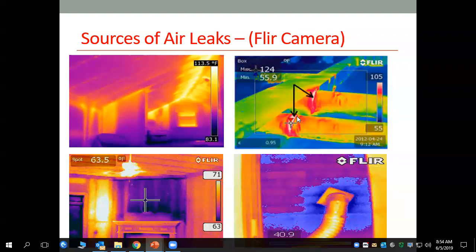And then on your connections here, on your duct where it's connected, there are obviously leaks. That could also be moisture at some point. That's on a long trunk line, and then the ducts are coming off. You see the fireplace, that's not sealed properly behind it. I'm not even looking at the actual fireplace itself, but there is a huge opportunity there to have a comfort problem because that's not insulated. And this is an outside penetration, if I'm not mistaken, related to fresh air for a fireplace, where you have a sealed combustion, and you see that we've got some issues here where it isn't sealed.